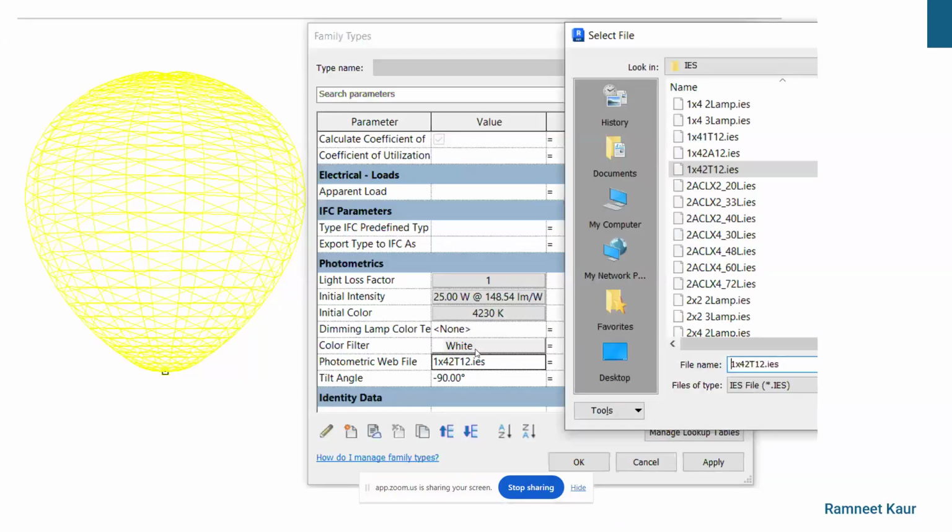Families have to be created very thoroughly. Here I'd like to show you that. So this is basically a nested family that we created. Families are category based, so you have to be very sure of the category in which you are creating. The first one that we had created, this single LED, is created on your light fixtures.